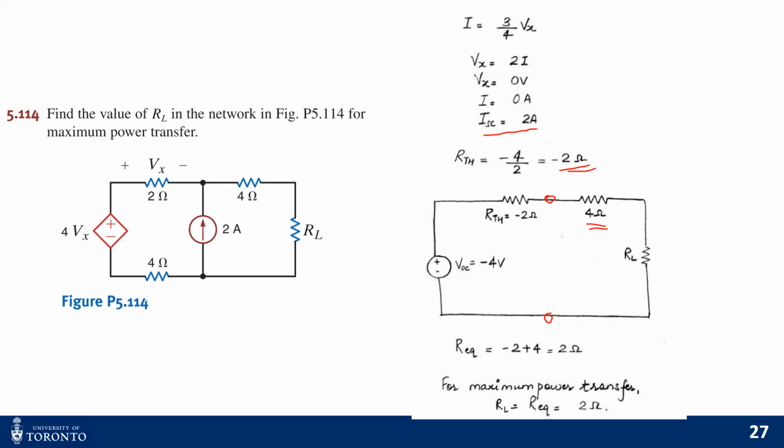So now, what is our equivalent resistance? Now remember, the equivalent resistance means that the RThevenin should equal the RLoad, right? But since resistance is a positive value, we take the absolute term. So RThevenin is basically 2 ohms, right? So our RL should actually be equal to 2 ohms, right? Now our original RThevenin, mathematically it came to be minus 2, right? And these 4 ohms additionally came up because we removed the load. Now if you sum them up, you also get the 2 ohms.